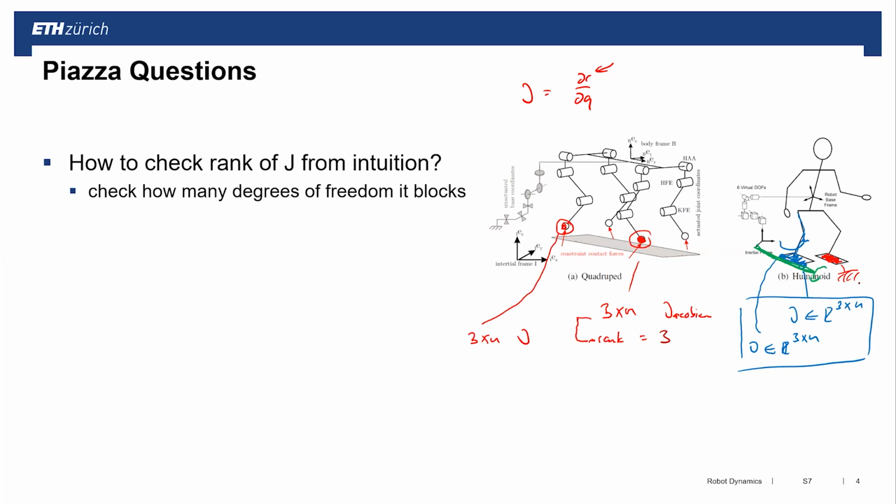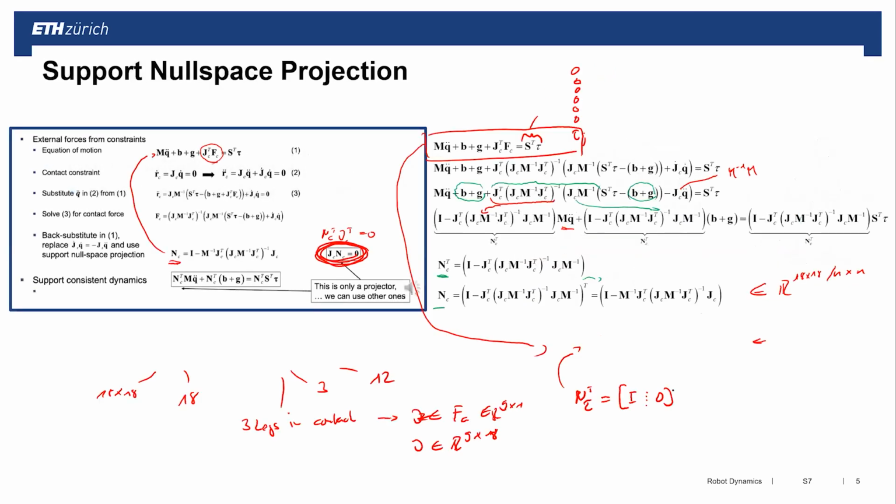The other thing is if you have both feet in ground contact, you have closed-loop kinematics. That's not easy to handle with minimal coordinates because the degrees of freedom in this closed loop are obviously influenced by the constraints. With the formulation that we have here, we have a very generic formulation that allows us to handle all these individual cases in one single formulation.